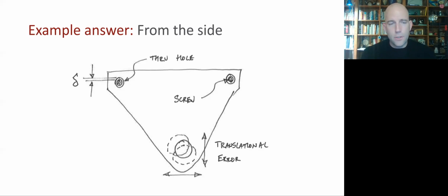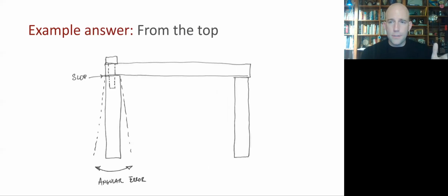So that's the downside of this approach. And another thing that can happen here that's a little harder to see in this picture, but is a little clearer for this similar approach, is that we have this error amplifier. In this case, it's similar to the previous, but we're coming down from the top through the horizontal plate. And in this case, we've got this long vertical plate and this thin section where the two plates contact each other. And the critical distances here are this long thing and maybe half the thickness of this vertical plate. And that becomes our error amplifier, L over, say, 1/2 T or something.